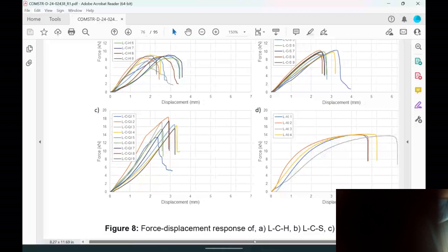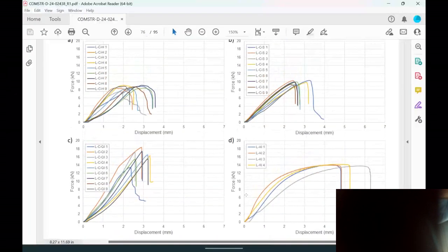So as you can see, just have a look. Let's have a look. These are the force displacements. So we've got the lug, we're just pulling it apart, measuring displacement and the amount of force. For the aluminium lug, you can see how it's behaving. Displacement, the force which goes to, let's say, 14 kilonewton. This is what industry is using. Landing gear is purely titanium, aluminium, and steel.